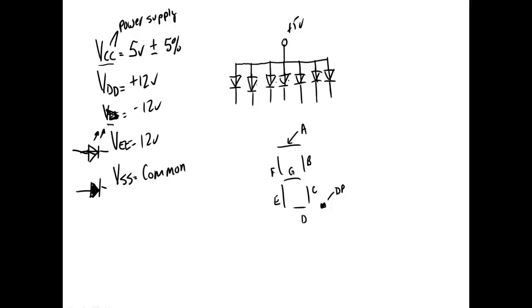So we'd come up here and connect this to 5. What would happen if I come over and connect this directly to common? Didn't we do that in class the other day? What would happen? Or did we do that in solid state? Didn't we burn one of these things up? Yeah. LEDs, when they're full diodes, once you exceed their barrier voltage, them suckers act like closed switches.